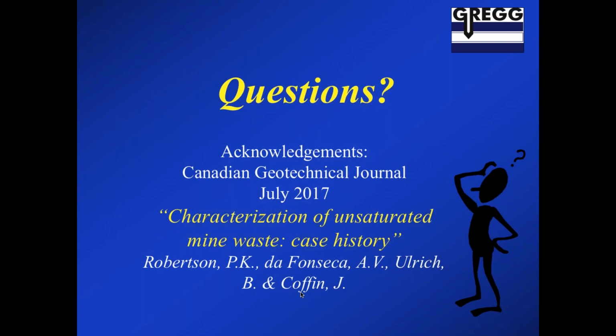But even with the seismic CPT, the deeper you go, downhole seismic becomes a little bit more challenging. And you saw that reflected in the scatter in both shear wave velocity and P wave velocity, which did increase with depth due to slightly decreased accuracy in a downhole seismic method when you go to these significant depths.